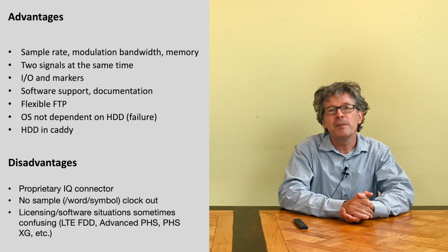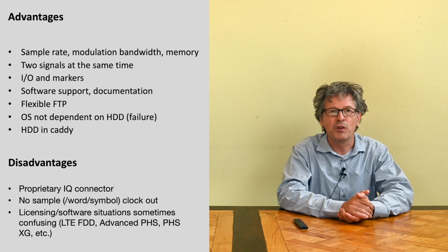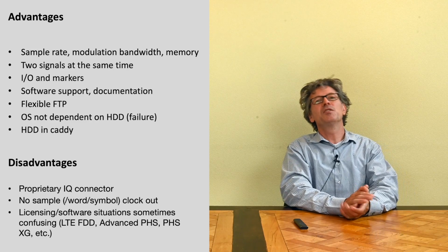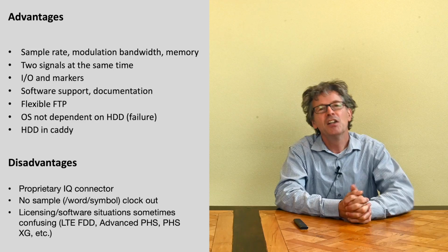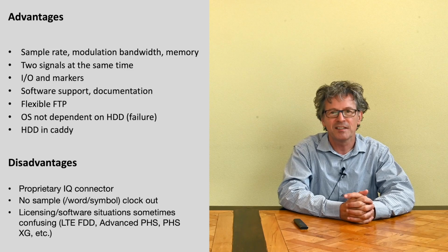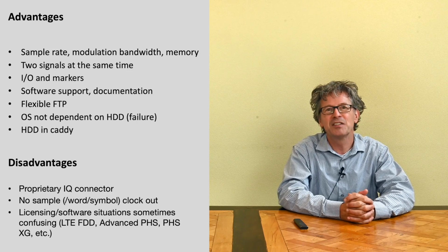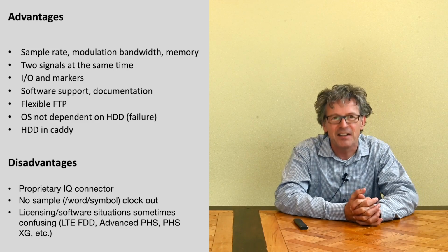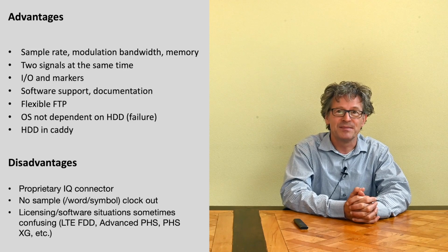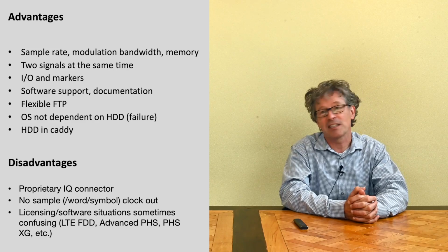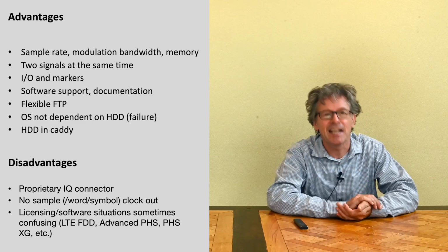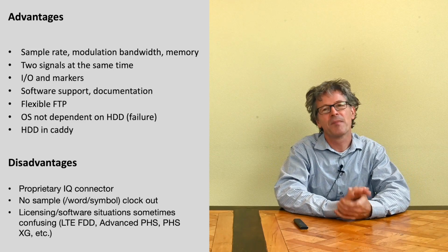I like the way FTP is being used on the device for moving all the files around instead of all types of proprietary stuff. And I also like that the operating system is not residing on the hard disk. So if you ever have a hard disk failure, you could still get another hard disk in, get it properly formatted, copy the waveforms from the Anritsu website or somewhere else, and you've got a working device again. With a lot of other devices from this period and even now, the firmware, the OS, resides on the hard disk. If something goes wrong there, you're doomed. And I also like that the hard disk is actually in a caddy on the back, so you can even just physically take it out easily.